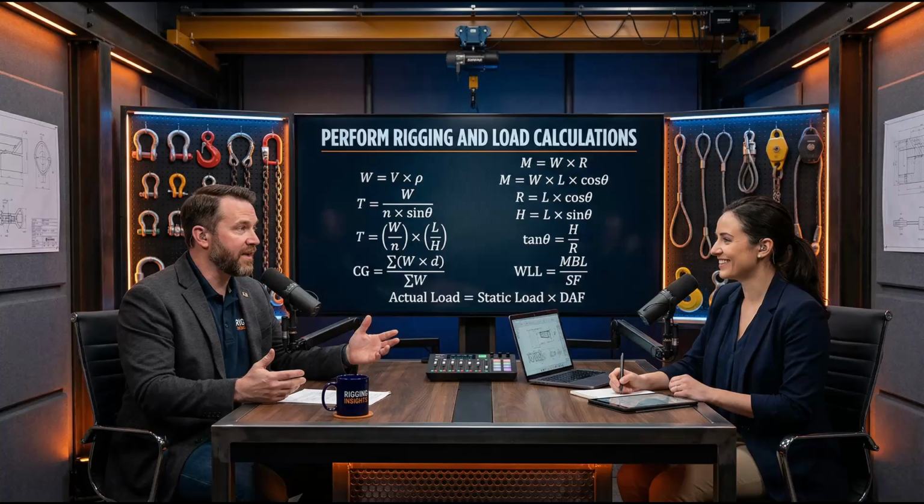weight. The crane hook, the wire ropes, and the lifting lugs experience the exact same violent trauma when a crane operator jerks the controls or when a load slips and is suddenly caught by the rigging. The Bechtel engineering notes quantify these dynamic amplifications with specific multipliers.